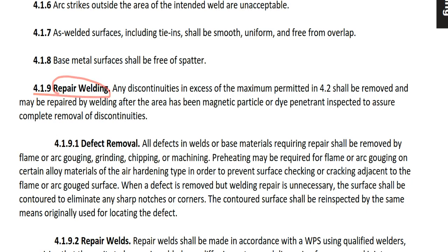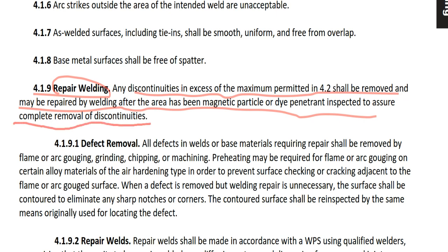4.1.9 Repair welding. Any discontinuities in excess of the maximum permitted in 4.2 should be removed and may be repaired by welding after the area has been magnetic particle or dye penetrant inspected to assure complete removal of discontinuities.